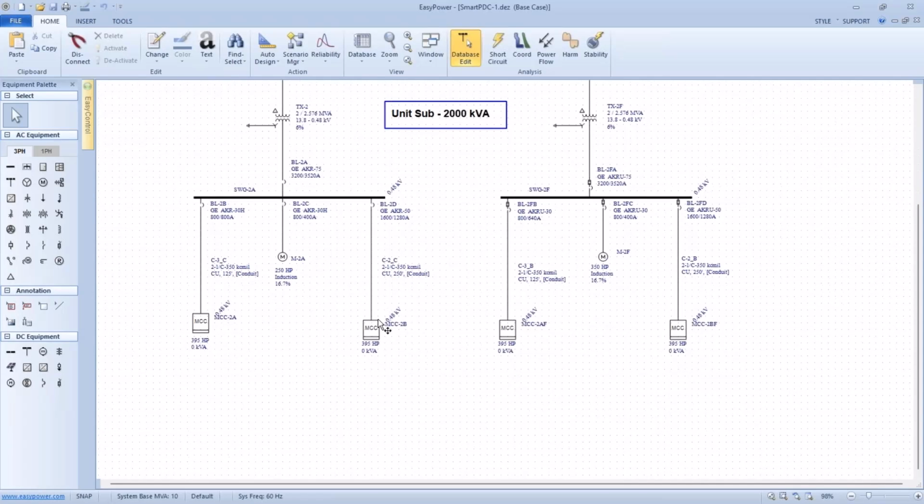First of all, in this case, this large motor is the largest load on this bus. So if I'm going to coordinate, I would coordinate against this motor load. Even though these are large total horsepower motor control centers, they don't have any single load as large as this one. So that's why when I'm coordinating for this bus, I do so with this as my primary load.